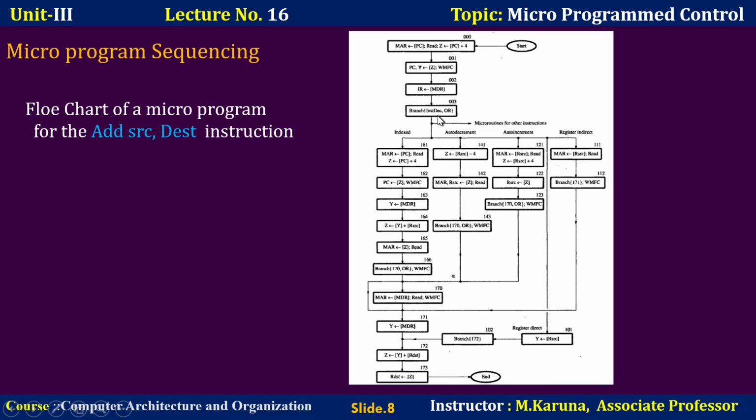Here the branch instruction decoder is used to select either one of the addressing modes of the data. Okay, so here an ORing operation is required to select either one of these, which is connected to indexed mode, auto decrement mode and auto increment mode. One OR operation can select either one of these inputs, and another OR operation is required to select these 5 kinds of addressing modes.